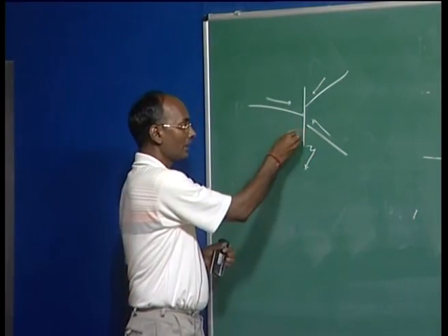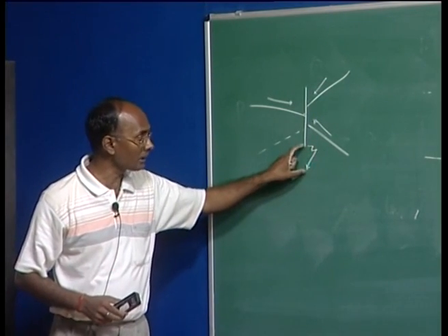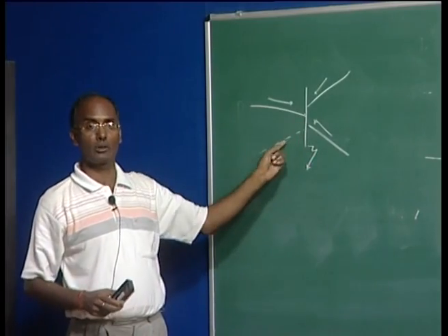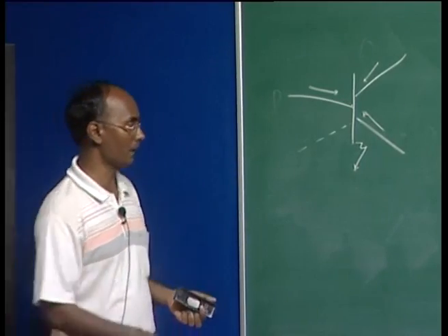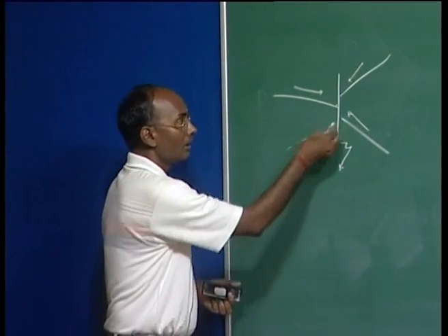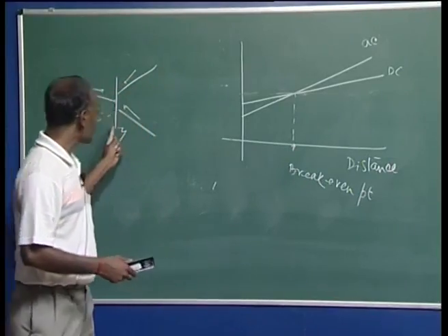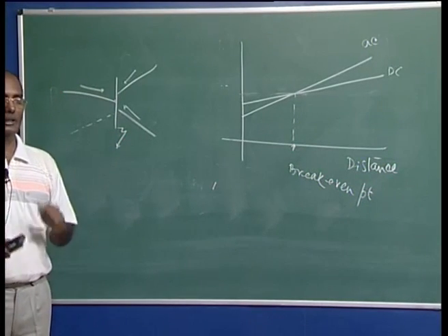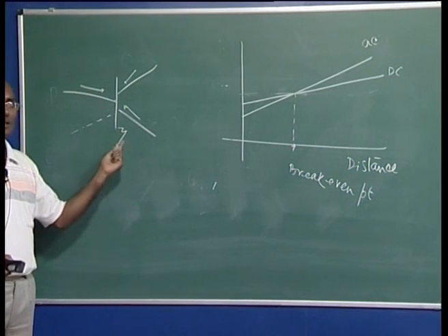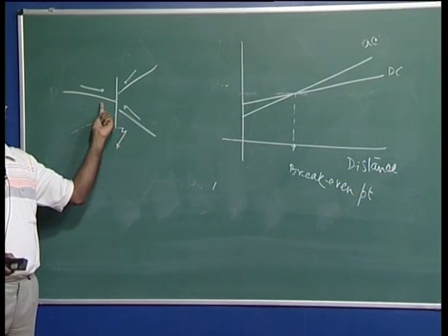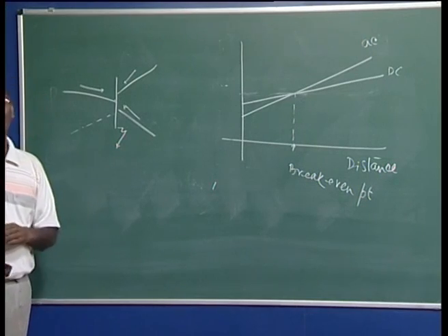So, if you connect another extra line here, what happens? The fault level of this bus will increase, because the impedance seen from this point to the ground decreases as you connect parallel lines, meaning the short circuit current will increase. There are many such locations, even in our UP itself, where many buses have many lines connected, and thereby there is huge short circuit current. So, if there is a bus fault, the circuit breakers must trip, and the rating of these circuit breakers is decided by this fault level.